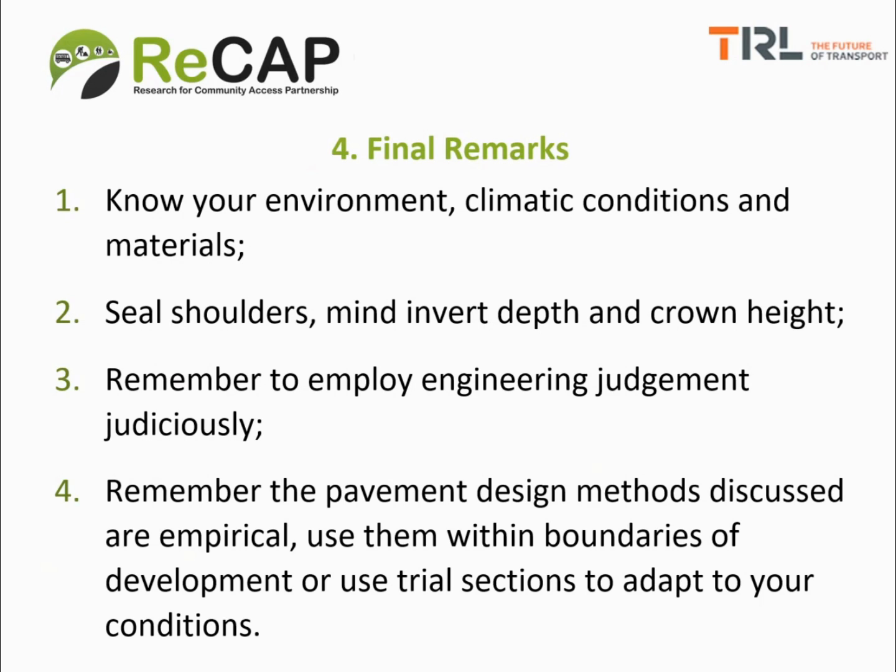Lastly, remember that the pavement design methods discussed here are empirical. Use them within the boundaries of the development of the method, or use trial sections to adapt these methods to your conditions or to extend the boundaries used to develop these methods.